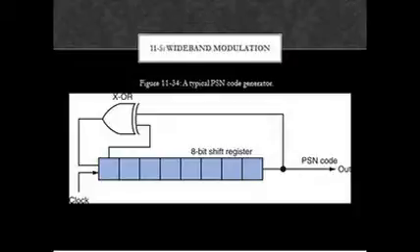In the figure, 8 flip-flops in the shift register are clocked by an external clock oscillator. The input of the shift register is derived by XORing two or more of the flip-flop outputs. The output is taken from the last flip-flop in the register. Changing the number of flip-flops in the register and which outputs are XORed and fed back changes the code sequence.